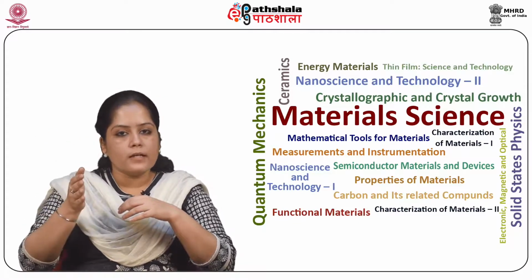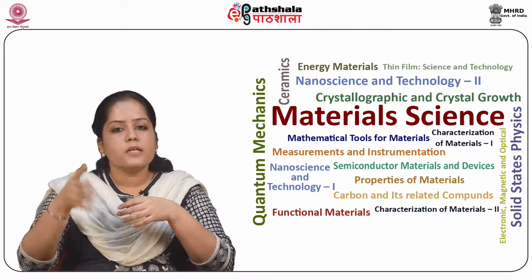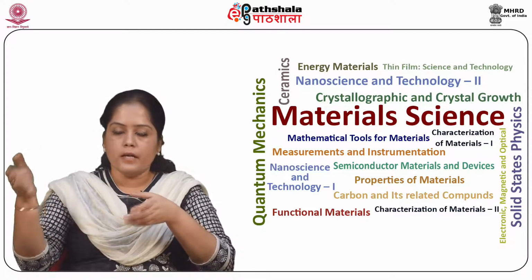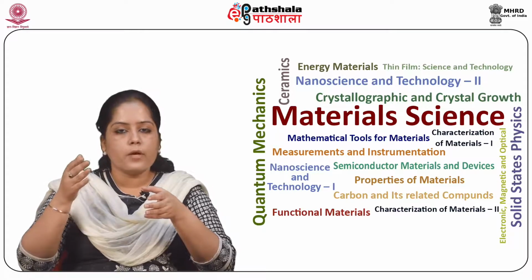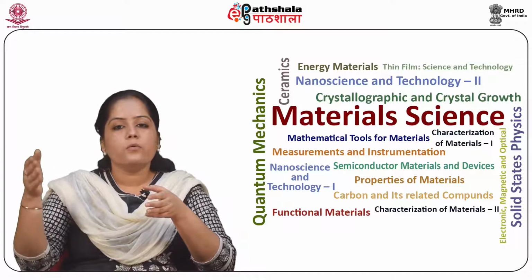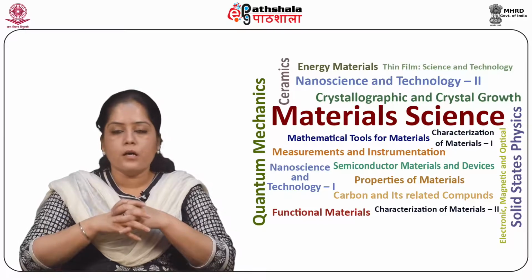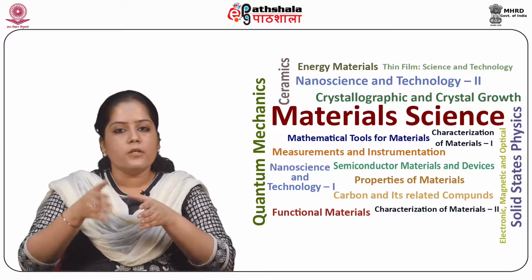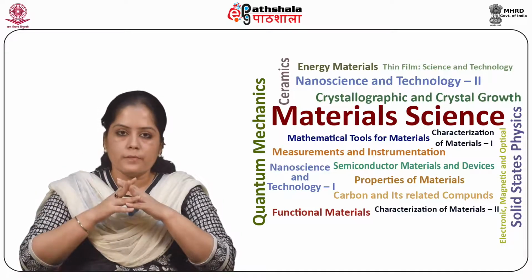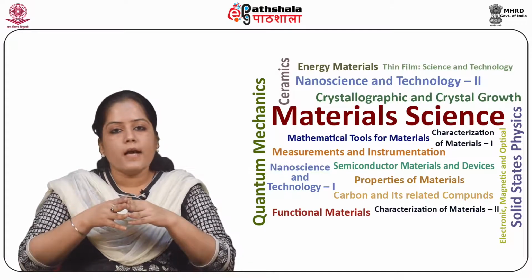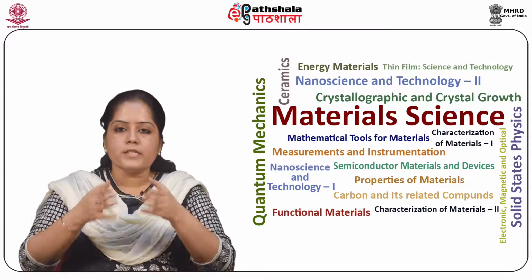So earlier we saw that the critical energy release rate for the fracture is Gc equals sigma c squared by E multiplied by pi a. This can be written in terms of Ki as Gc equals sigma c squared by E multiplied by pi a equals Kic squared divided by E. So this implies that the fracture would occur when Ki reaches a critical value Kic, since the energy release rate would reach the critical value for fracture. The quantity Kic is called the critical stress intensity factor or the fracture toughness of the material.